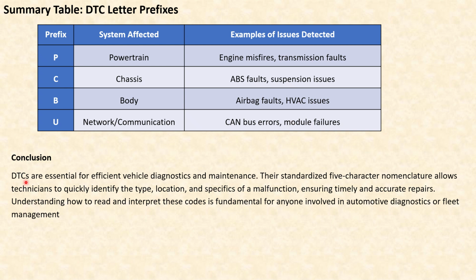Now, conclusion: DTCs are essential for efficient vehicle diagnostics and maintenance, and their standardized five-character nomenclature allows technicians to quickly identify the type, location, and specifics of a malfunction, ensuring timely and accurate repairs. Understanding how to read and interpret these codes is fundamental for anyone involved in diagnostics or fleet management.